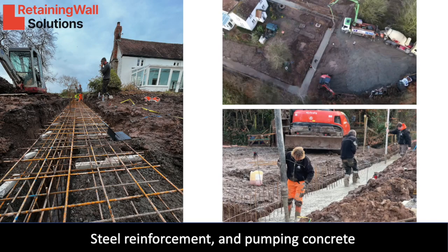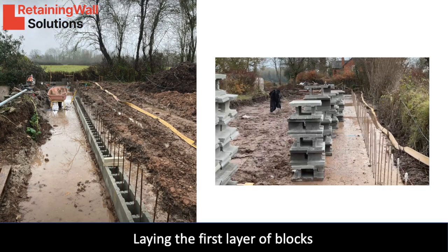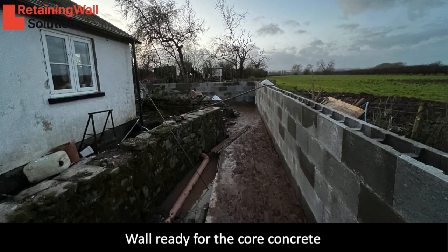On this slide you can see the foundation, steel reinforcements and the concrete being poured in the foundation using a concrete pump. This slide shows the first layer of blocks having been laid. And this slide shows the wall built and waiting for the concrete core to be poured.